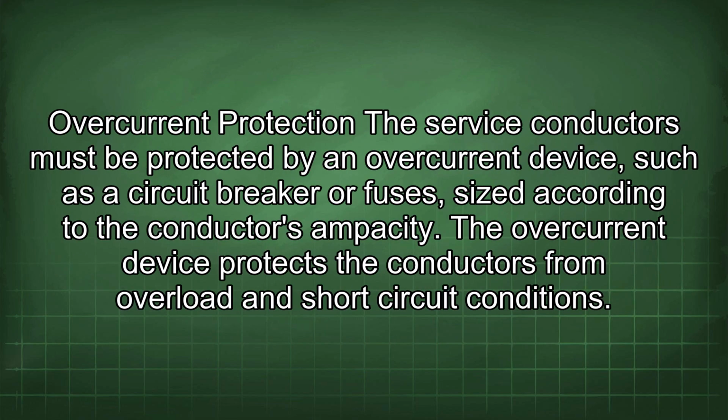Overcurrent protection: the service conductors must be protected by an overcurrent device, such as a circuit breaker or fuses, sized according to the conductor's ampacity. The overcurrent device protects the conductors from overload and short circuit conditions.